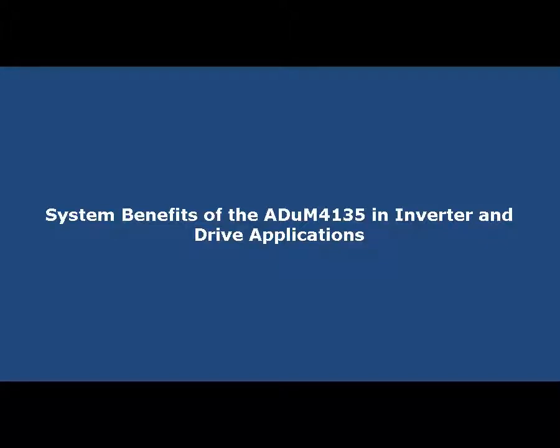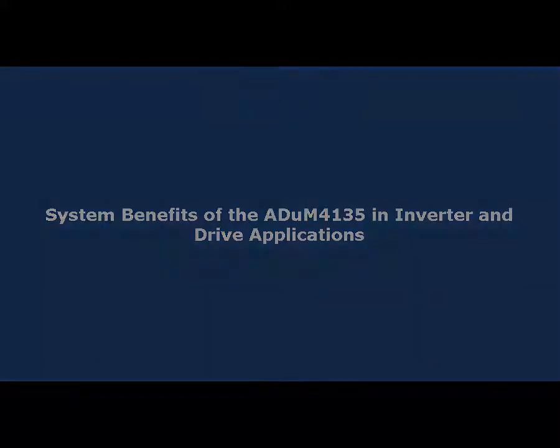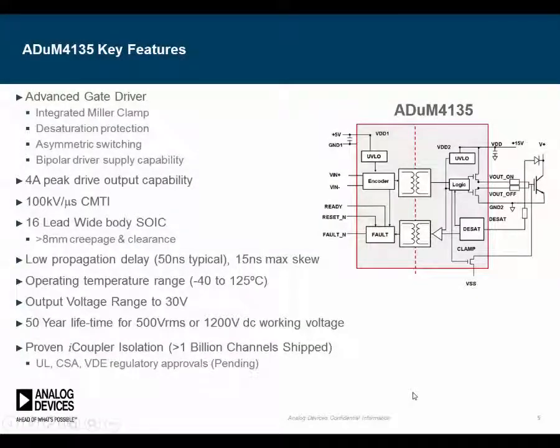Let's look in more detail at the ADuM4135 isolated gate driver and a couple of the system benefits that this part can bring to the motor control drive developer. The ADuM4135 from Analog Devices has some key specifications related to IGBT protection and to the timing performance of the driver itself. We will consider both of these specifications and their system impact.